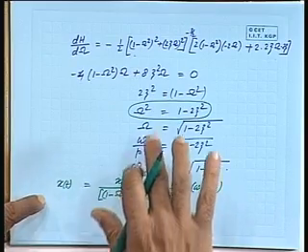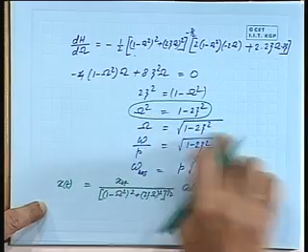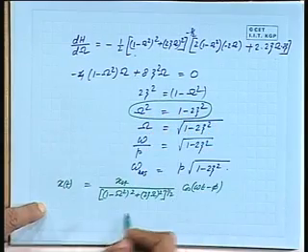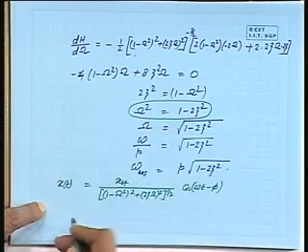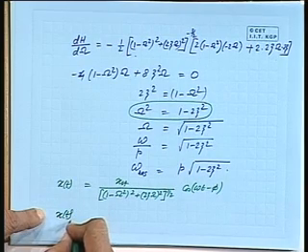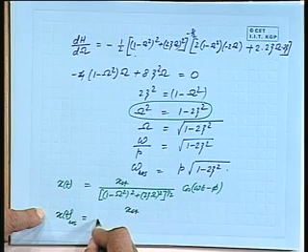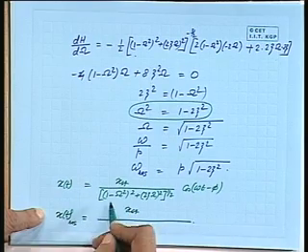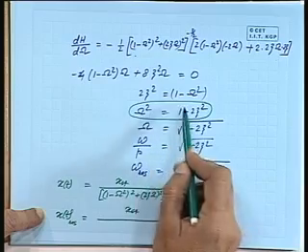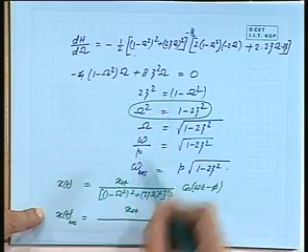Now, if this is going to be the resonance frequency, this is the ratio and this is the ratio square. So, ratio square, if I substitute from here, I get the response for resonance here as: 1 minus omega square I have already calculated, so this is 2 zeta square.